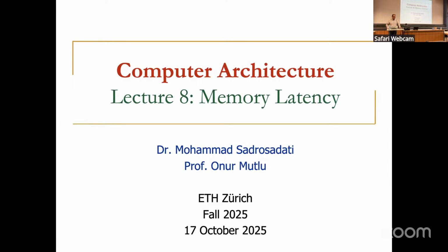In many, many cases, because of the high latency that we have in our system, we design different techniques. Think about cache hierarchy, for example. Think about prefetching. Think about high-cost interfaces that we have in our systems. All of them are there just to provide enough parallelism such that you can hide latencies. So if you don't think about solving the core problem, you're going to still be working on solving the latency hiding problem, which might not be efficient enough.